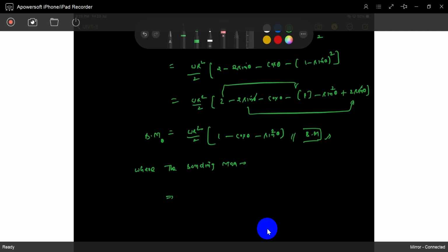If bending moment is maximum, shear force is either maximum or minimum. That's it, na? So you can set that where the bending moment is maximum, the differentiation of bending moment with respect to theta, these all quantities in theta not x, is going to be 0. So with respect to theta, differentiation of bending moment means what? Shear force. Shear force is compulsorily turned into 0.